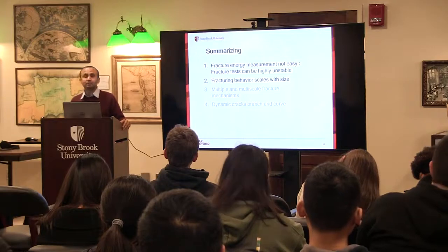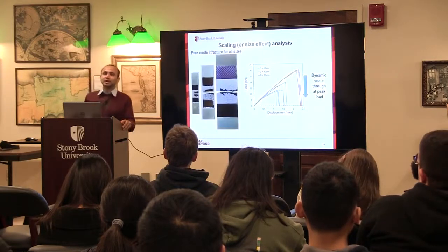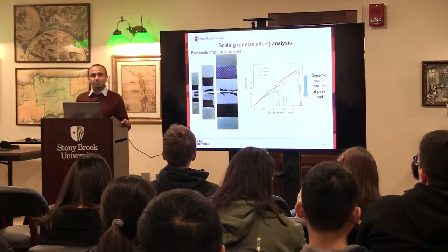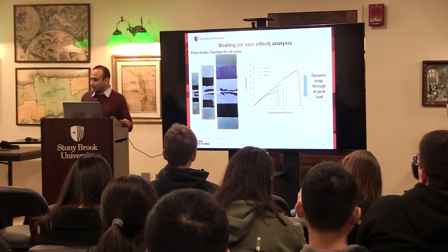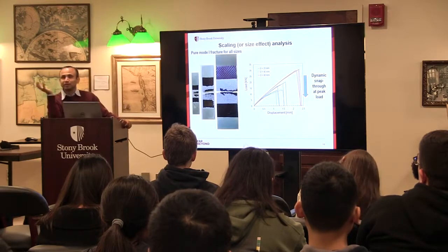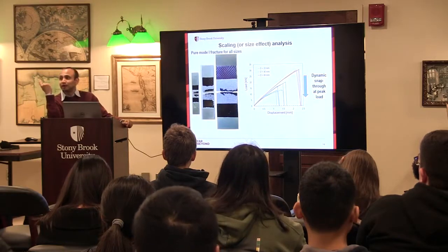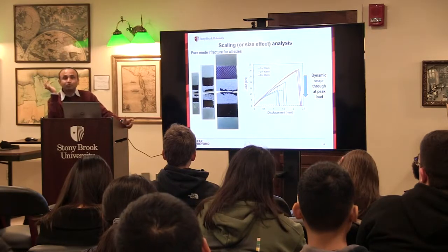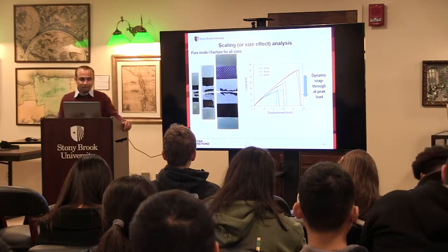measurement and the scale. And it turns out that both of these challenges can be tackled together by doing something called size effect analysis. Now conventionally people are used to doing tests with just one sample size. That is no longer applicable or valid for composites. You have to test samples of multiple sizes. That is what we did here.